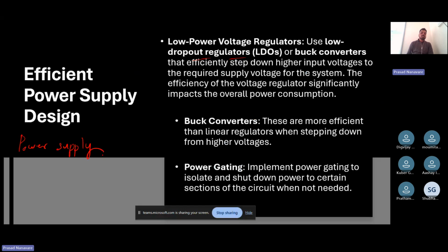you would know that the first phase will be to step down the voltage. Okay, if we are having 230-volt AC mains, then our small systems won't be able to take it. So using a transformer, we basically step it down. Then we have rectifier circuits, then we have filter circuits to filter the signal further. After this, what we have is a voltage regulator.